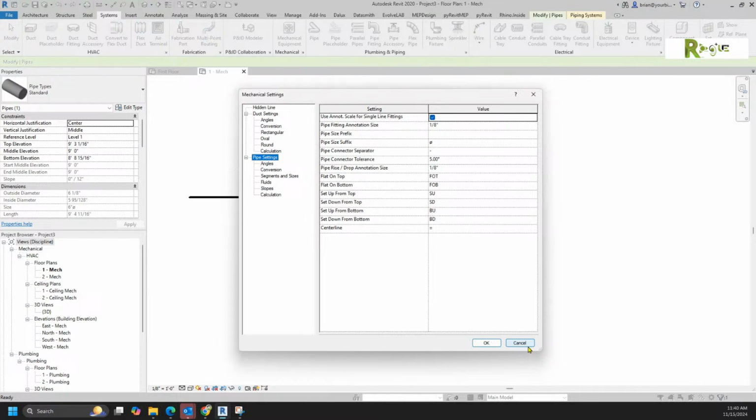So one of the things that I've had great success doing is, in the valve, I have a little checkbox. If that thing needs a flange on one end or a flange on the other end, it turns it on right there at the valve. The reason I had to make it so it could turn on at one end and off at the other end is if that valve was coupled to another piece of flanged equipment, because then you would need another flange.